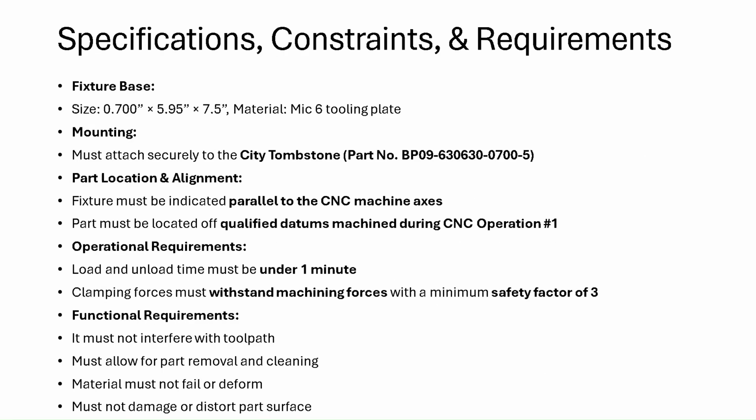Now we have the specifications, constraints, and requirements. First, the fixture base has to be within the size specified on the page there. Then mounting, it has to be securely attached to the tombstone. The part location and alignment has to be indicated parallel to the CNC machine axes. It must also be located off qualified datums machined during CNC operation 1.